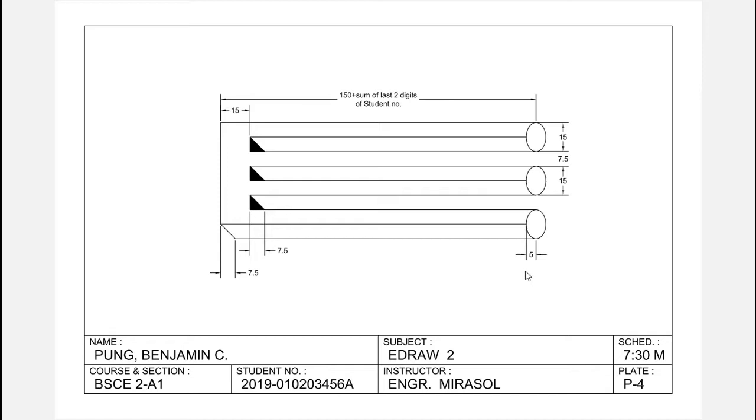Also here you would see that this is an ellipse. The major axis is 15 units, and the minor axis is 10 units, 5 from each side. Okay, so basically this is what we're going to do. Also, we need to put hatch or this shading. These are called hatch patterns in AutoCAD. This is an ellipse. Okay, so let's see what we can do.